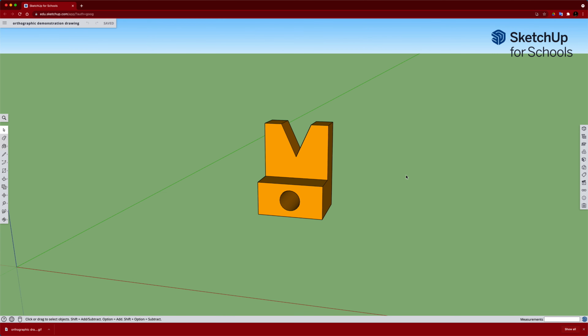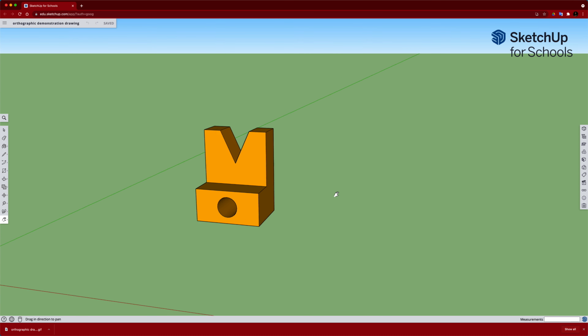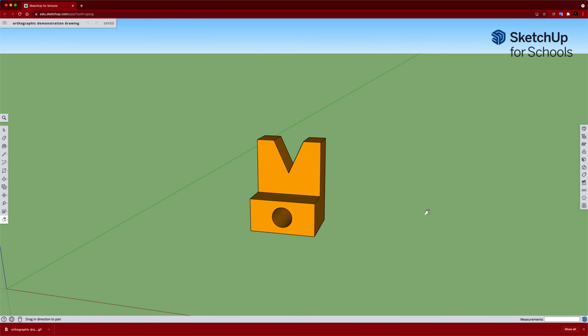Panning means moving left and right and up and down. Okay, so to do that, you'd think you'd use P, but that's for a different command called push-pull. So for SketchUp, it's H, which turns it into this hand. And again, I can just press down on the left mouse button and pan to the left and to the right and up and down. Again, spacebar to go back to the selection tool.